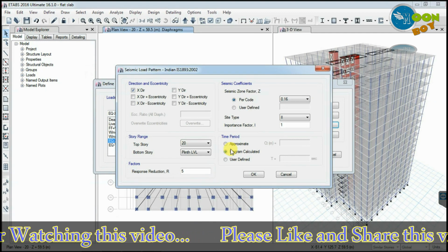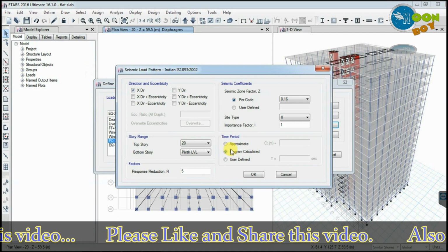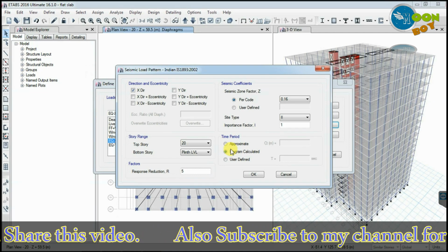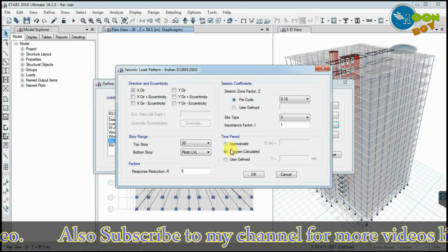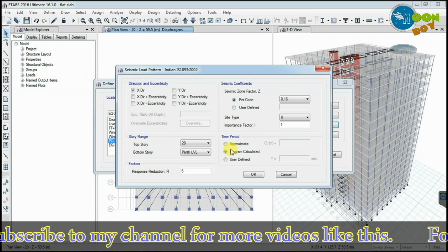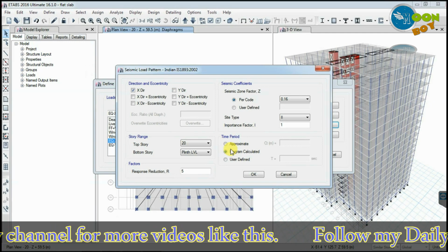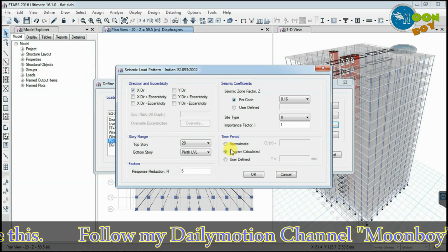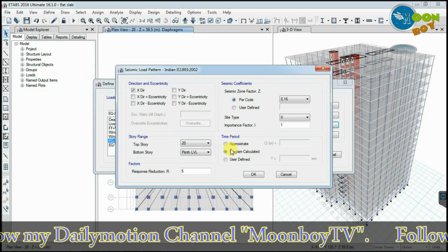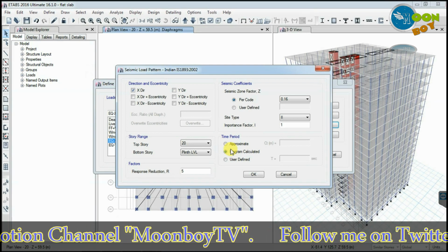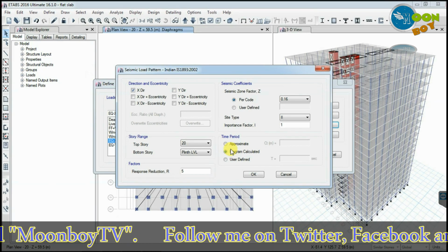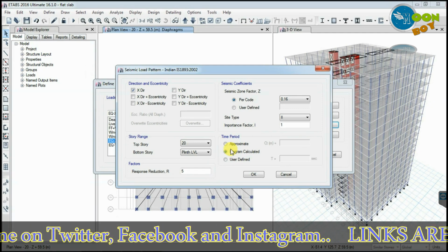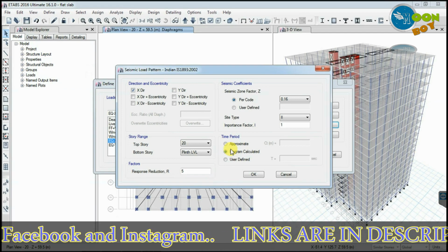We can take it, but if you take eccentricity, it will be difficult for you to calculate all the scale factors in the response spectrum, because in response spectrum you are not going to consider any eccentricity, right? We will be having response spectrum in x direction and y direction, two directions. Then if you take eccentricity, again you have to provide that eccentricity ratio for all the diaphragms. Oh, okay, sir.